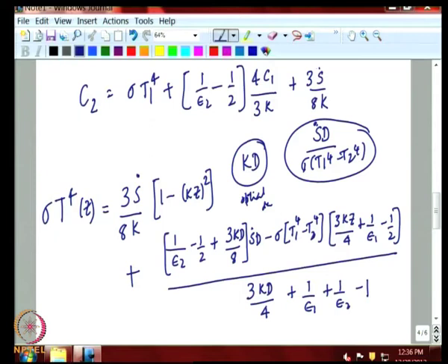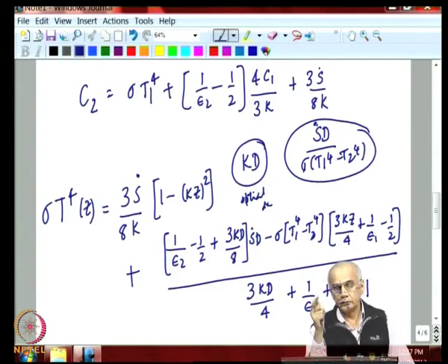So, this particular consequence is happening in the optical thick limit, and when the internal heat generation dominates over the wall flux, then you find in the optical thick limit the high heat generation inside the enclosure makes the temperature distribution almost uniform, and the effects of the wall are only seen very close to the two boundaries as a jump condition.